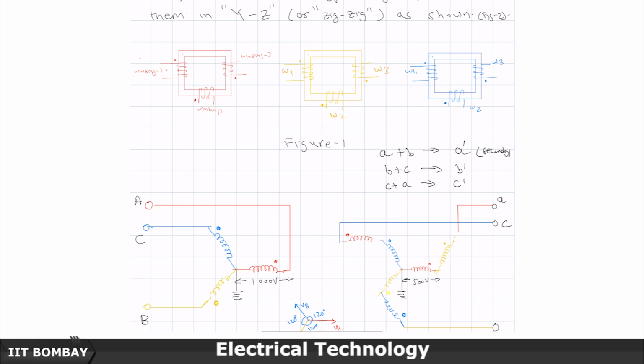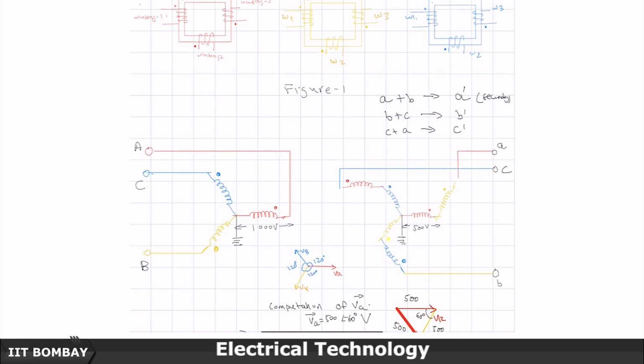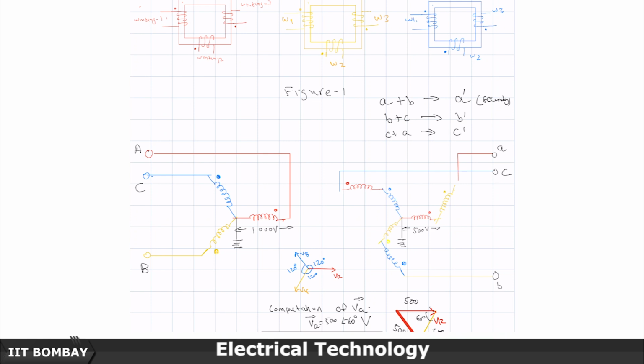And this is the C phase. If I apply 1000 leading 120 degrees, then I will get 500 leading 120 degrees here and 500 leading 120 degrees here. Now, look at what I have done on the secondary side. This side is my primary side of the 3-phase transformer. This is the secondary side of the 3-phase transformer.